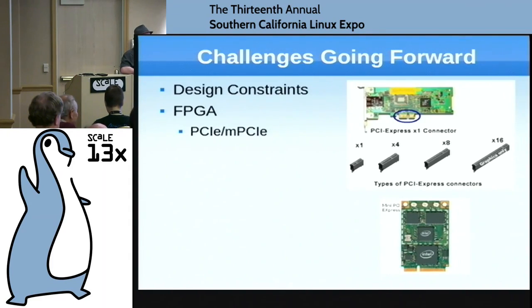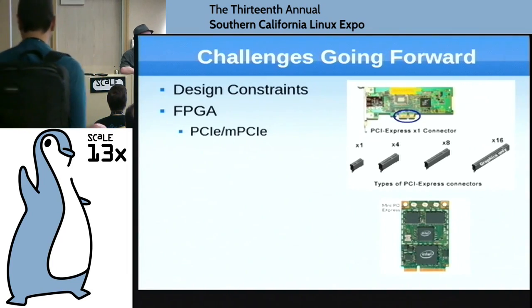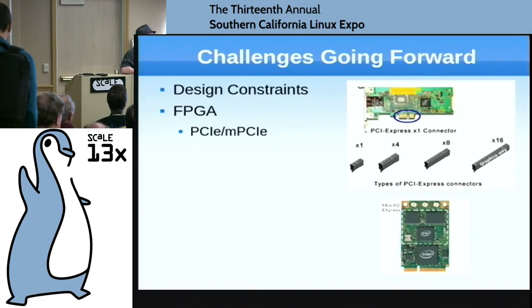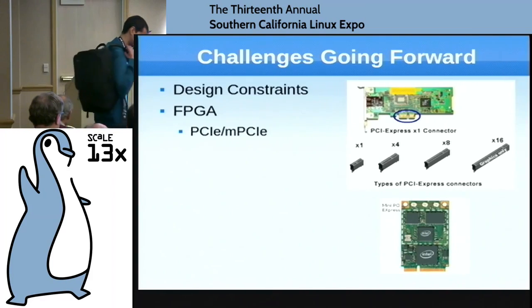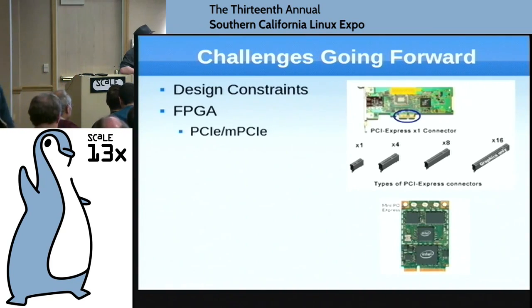To debug and test these, they are differential pairs. They have to have matched lengths, matched impedance, and they operate at very high speeds, which puts them out of the reach of most people to create open tools to debug these items. It's important because there are a lot of libraries already existing for FPGA that support PCIe, and all you have to do is load that library and create your own software for your specific use case.